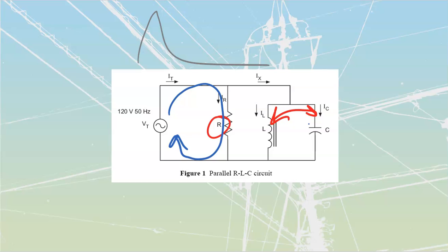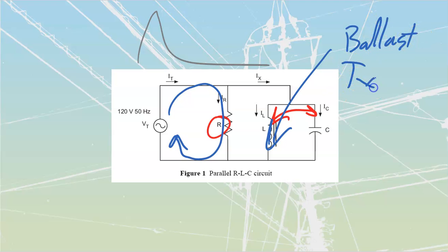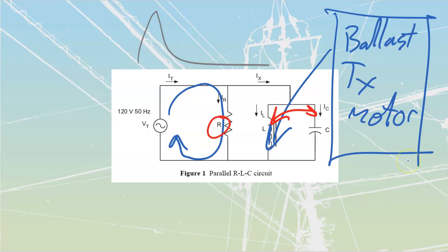Now, it seems pointless because we don't know enough about our overall electrical systems yet, but we do have a lot of electrical systems that are going to be inductive. Ballasts, transformers, and motors are all going to need to use magnetic induction to operate, to transform voltages, to create light, to create rotational movements, etc. Because they're all going to be inductive, we don't want to leave those inductive VARs loose on the system, so in a lot of cases we're just going to place caps on it to cancel those things out.